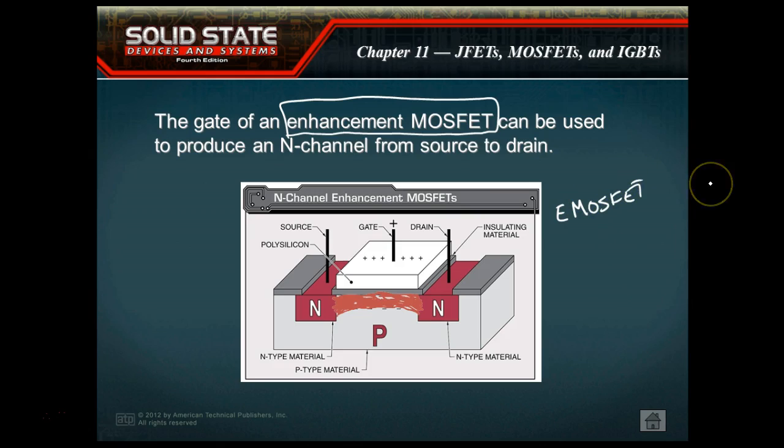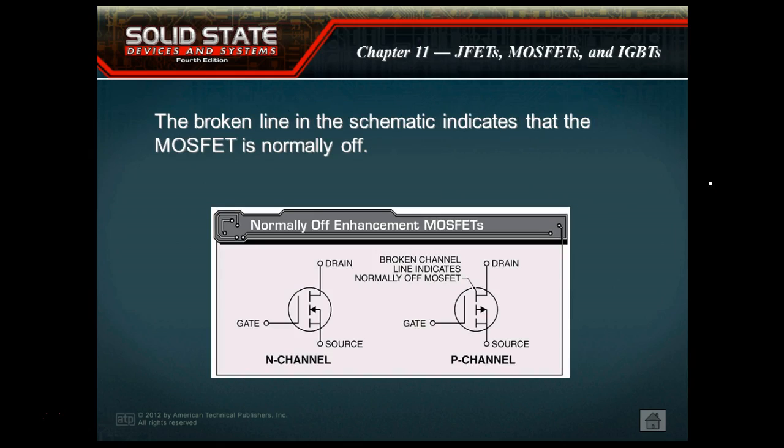Used predominantly as a switch, a very high-speed switch. Has extremely high resistance when it's turned off between the drain and source, and has very low resistance when we turn these puppies on. So we use these as switches all the time. These are the predominant guys used inside digital circuits, in microprocessors, and in variable speed drives, or variable frequency drives, which we'll look at later.